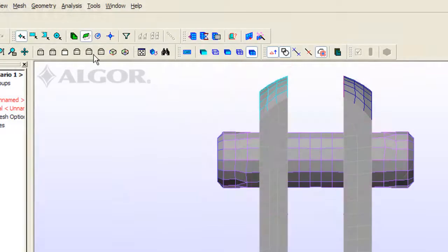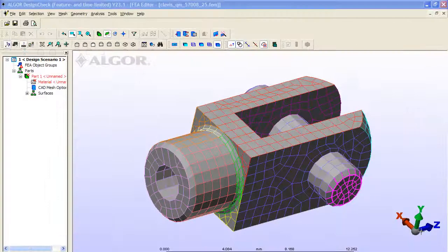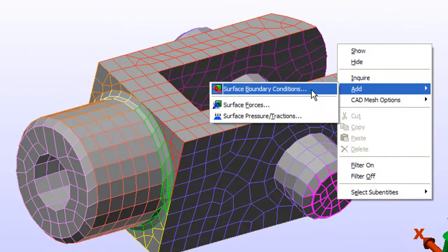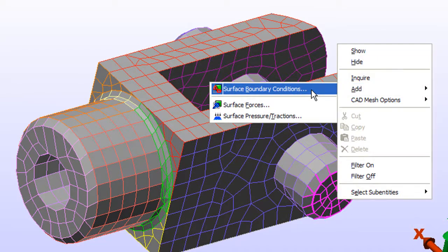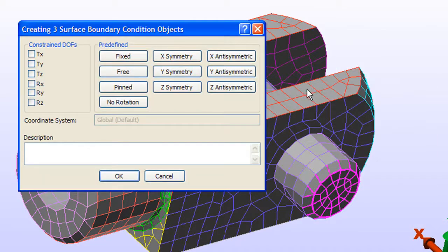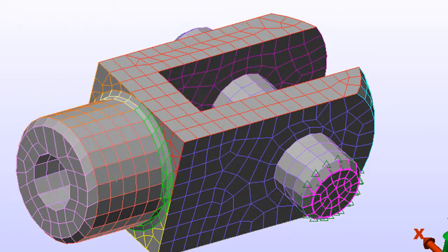Now that the meshed part is ready, I'll identify a surface as a fixed corner. I did that simply by picking the surface selection tool, then the rectangle selection command. And I also did the same thing on the opposite side. You can now see that I've applied surface conditions by the little arrows that now appear on both sides of this little bar.